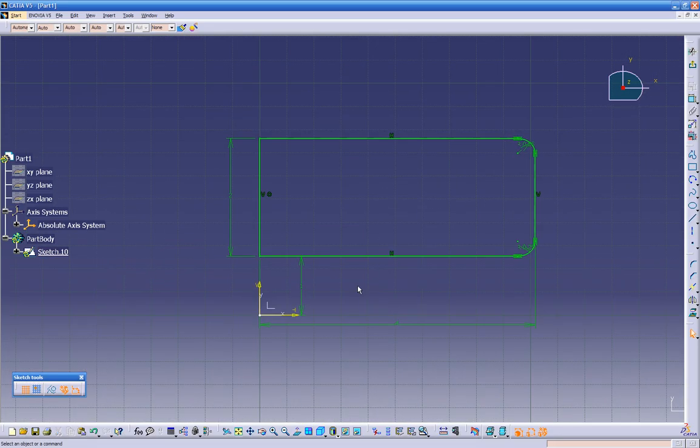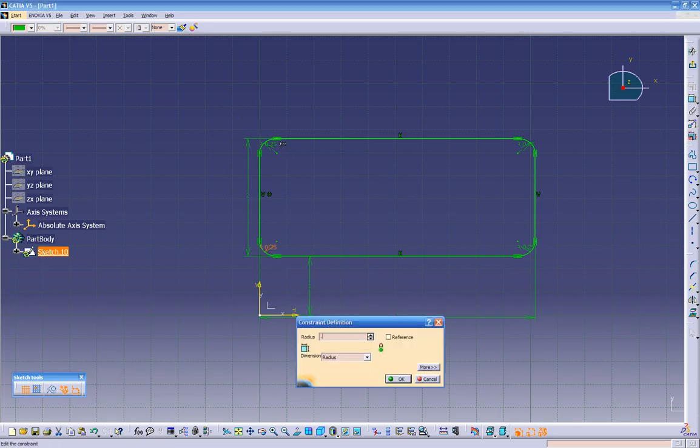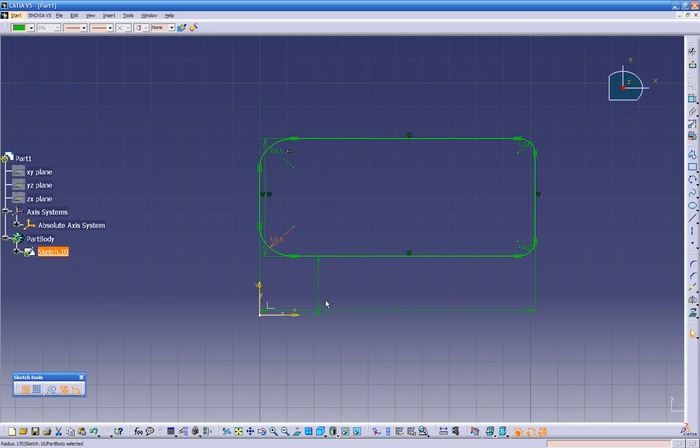We can highlight all the points, just drag your mouse. Let's highlight this, click on the corner. We got our points selected. Let's give it a dimension 250, and there we go. And as you see over here, we got a little formula right here. So that means if I change this right here, automatically it's going to change the one on top.